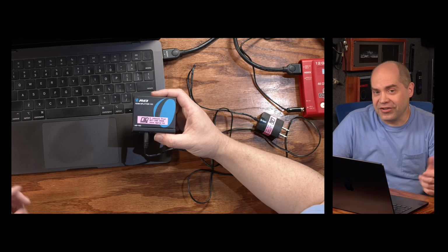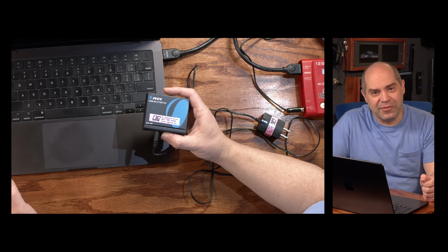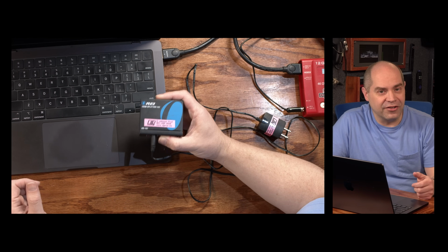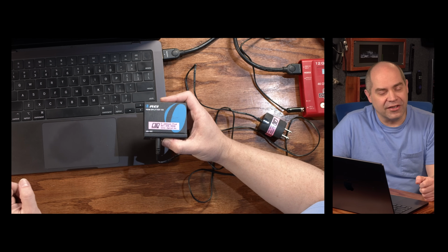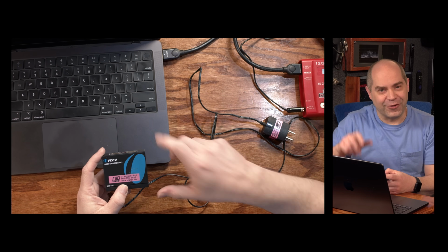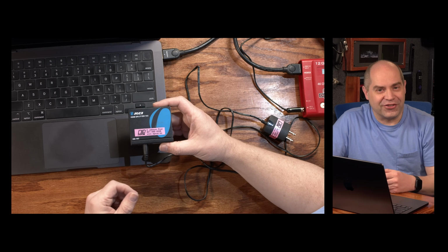So if nothing else works in a particular situation, you can always take an HDMI splitter like this, add that to the signal chain, and again, I've had a very high degree of success doing it that way instead of trying to make a direct connection from the HDMI on the Mac to a converter. So, another tool to add to your arsenal.